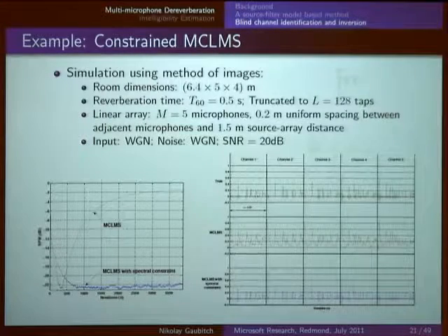I should mention, the NPM is misalignment, but normalized. So that's an oracle kind of measure, and it's used quite often. It's the same as misalignment used in normal channel estimation, but it normalizes so that you avoid any scaling effects. If the channels are scaled differently from the estimates, it takes that into account. I have looked at some ways of trying to find where this point is, because it would be a good idea to find it and stop here, but it becomes quite tricky.